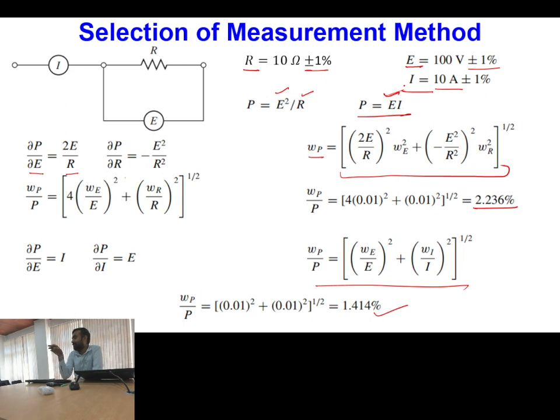Once you have chosen the flow meter, from the data sheet of the flow meter you will have some uncertainty mentioned, plus minus 1% or 2% or so. Likewise, you have some other uncertainty in measurement of a second parameter, and a third parameter. Then, to calculate your resultant, you will first identify all the formulas from your theoretical framework, and then using these formulas for measurement of the output, you will first do the uncertainty analysis.